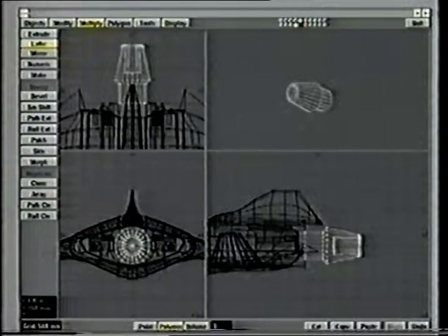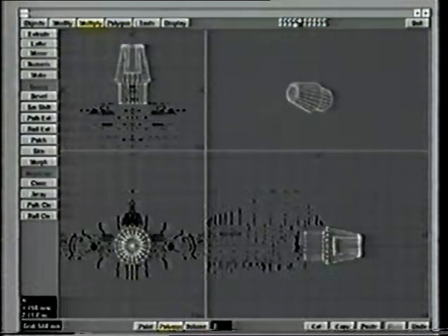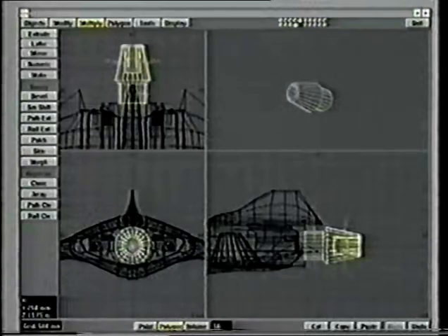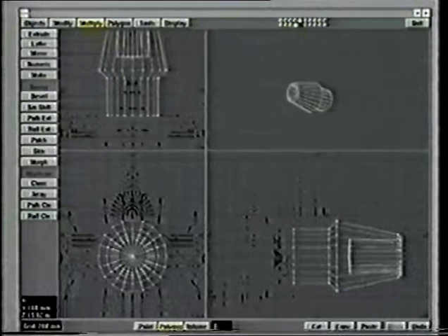So, zoom in a bit. Now once again, I want to do the selection of the polygons. Notice they're all pointing inwards as well. You cut that and paste it back. Just hit the F key to flip them so everything's pointing outwards, the way it should be. Let's just zoom in a little bit more.